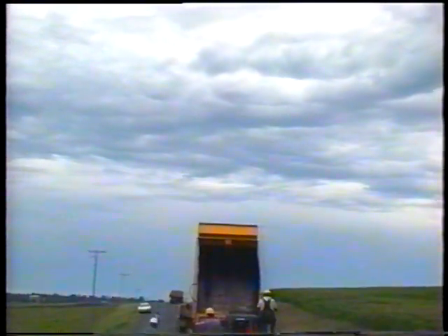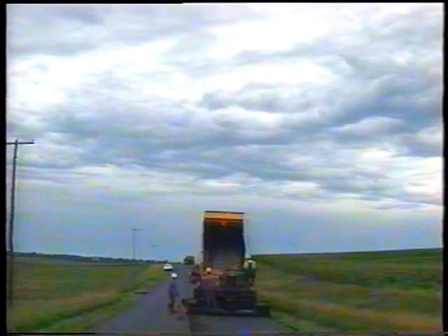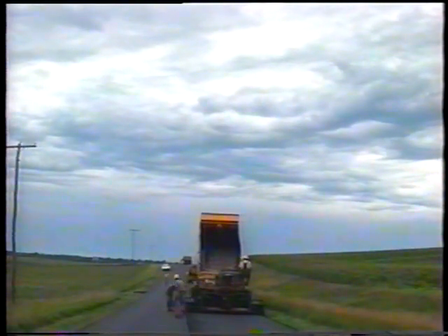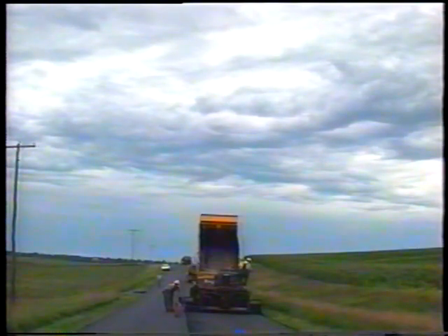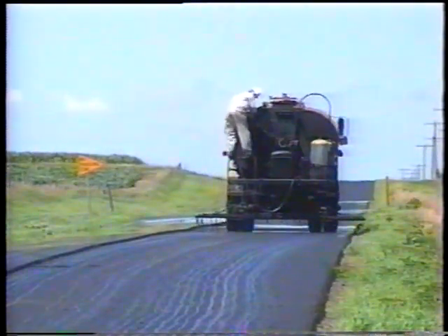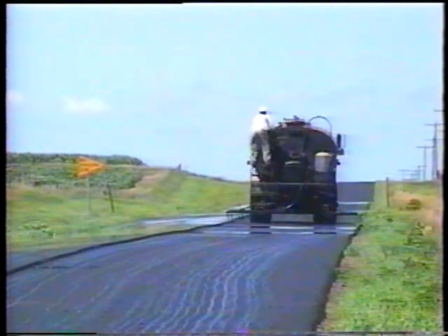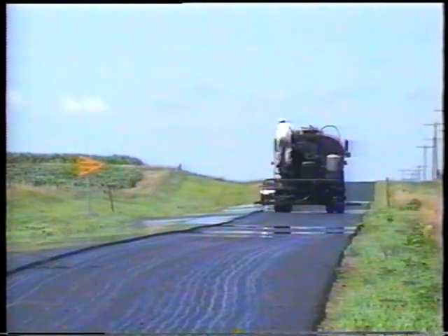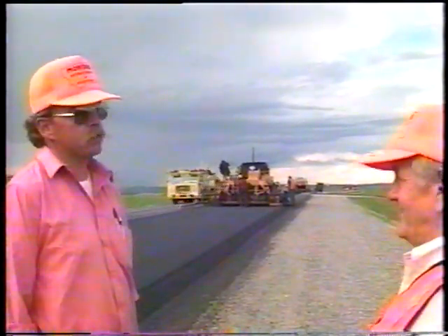Precipitation is a concern. Asphalt paving should not begin when rain is about to fall or too soon after it's fallen, while the surface is still wet. Occasional sprinkles or passing showers have to be dealt with according to their volume and duration, from working right on through the minor ones to temporarily halting for the more serious ones. Winds by themselves may not be cause to avoid paving, but they sure can mess up the tack application and cool down the mix real fast. So use good judgment. If weather conditions prevent good work, take the necessary action.